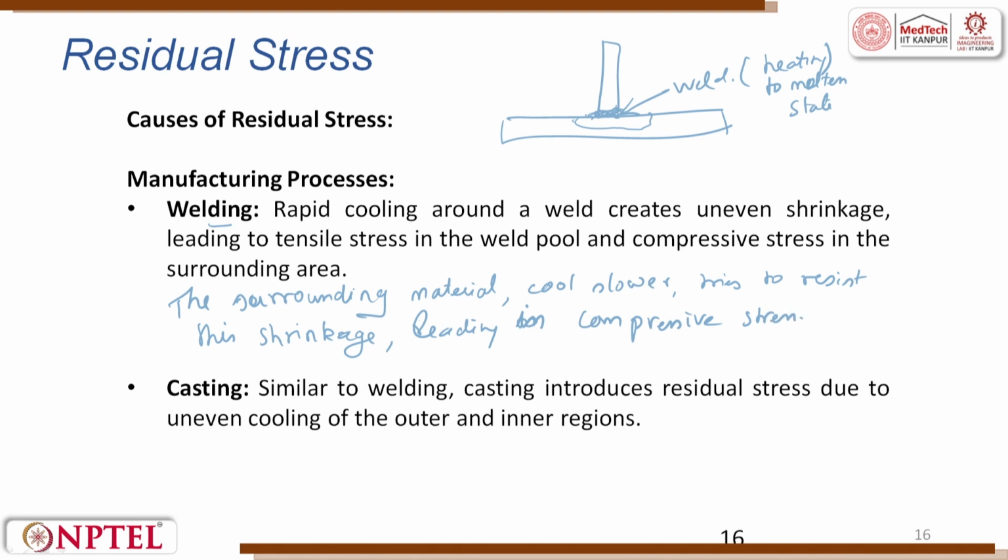Okay. So, when you heat and there is rapid cooling, tensile stress arises; when it cools, it tries to pull material. The surrounding surface has a larger area, so the heat flux is low. So, the surrounding material slowly cools. That tries to resist the shrinkage, which leads to compressive stress.